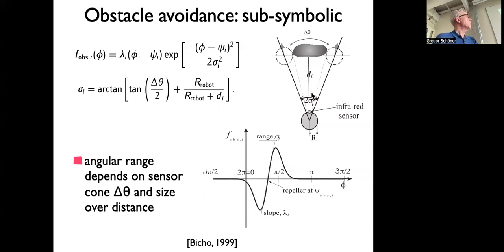Sensor range, but it's important that you take into account that you really want to avoid that whole sector. So the maximal obstacle that would exactly sample that angular range, you have to avoid that, which would mean that there has to be half a vehicle size on the left and half a vehicle size on the right that you also want to avoid.